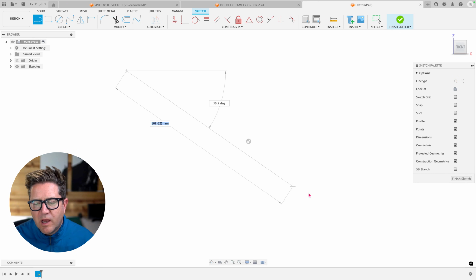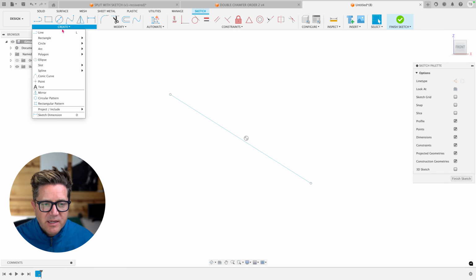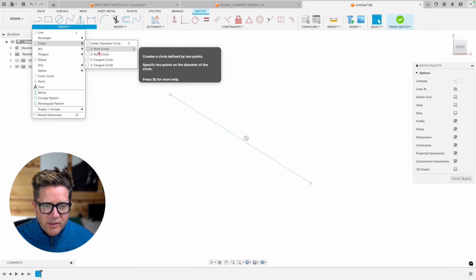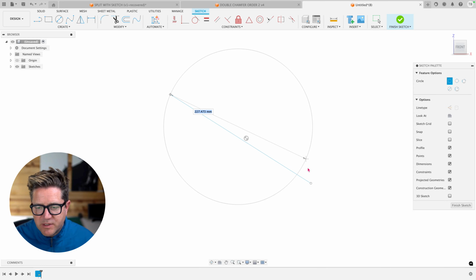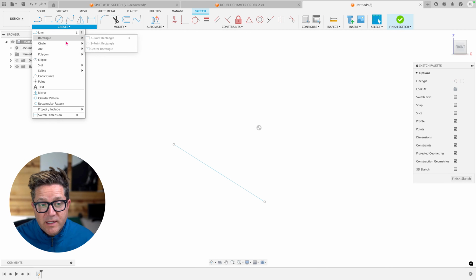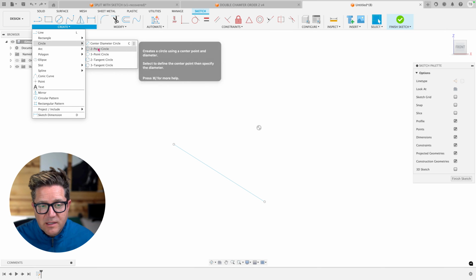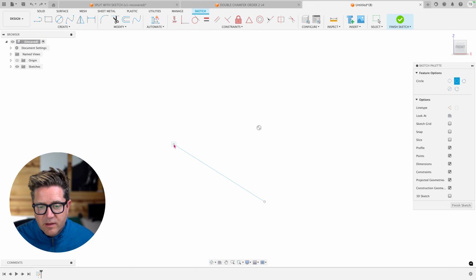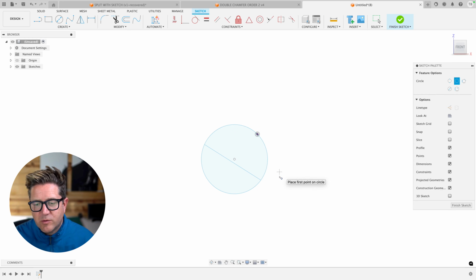When it comes to aligning to a specific line, where you have 2 points that you care about, that's where the next option of 2-point circle is great. Simply select the 2 points, and it will connect to those. And now if you wanted to hit all 3 points in this design, where you've got the 2 from the line and the origin, you click all 3, and it will align to those 3.